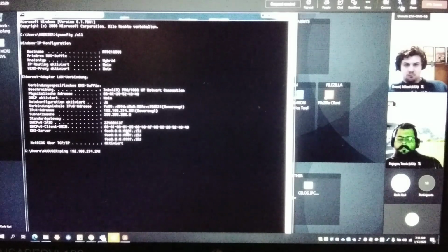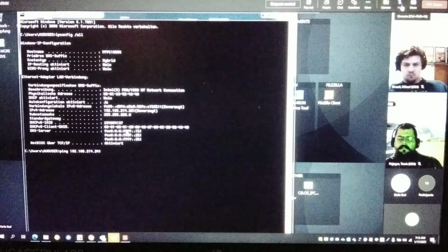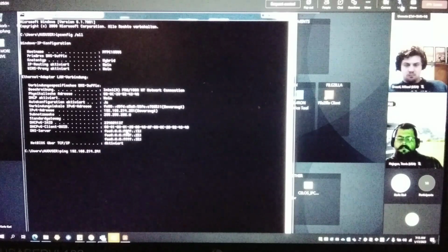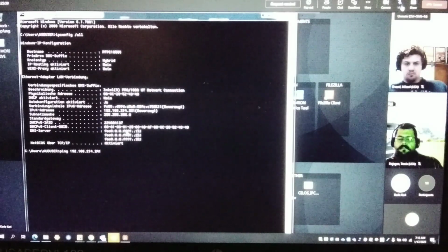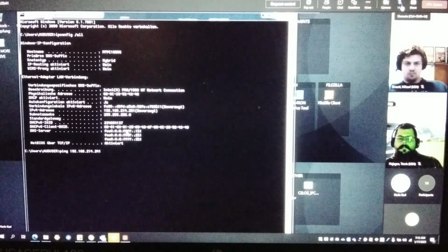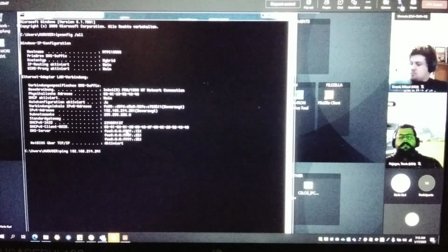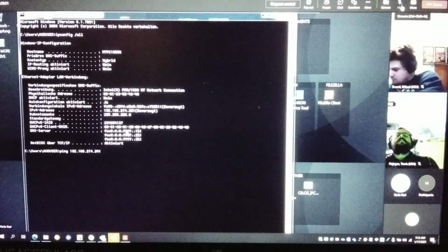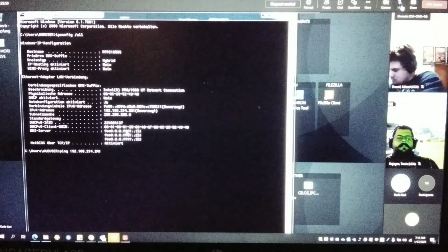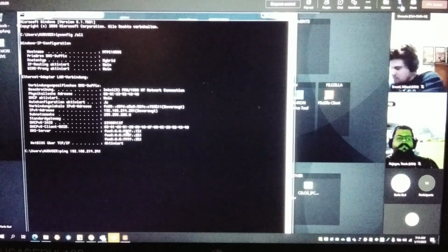Always the Windows-based unit has referred the host IP address 241. Okay? And so that means if you would like to be connected with your service laptop to the system network, independent of the control edition, how old the control unit or the machine is, with this IP address, you will always be connected to the Windows-based system, okay? On every numeric control, okay?